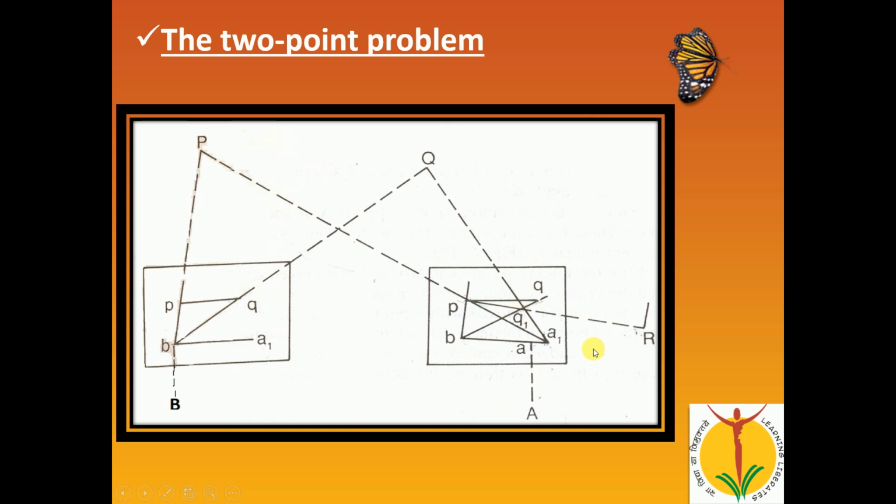Alidade touching point b, we are going to bisect the ranging rod at A, and we are going to draw a line, that is bA1, and we are going to measure the distance between b and A, and that distance we are going to mark here. Next thing, we have to move the table. After moving this table we have to transfer the point A1 exactly onto the station A.